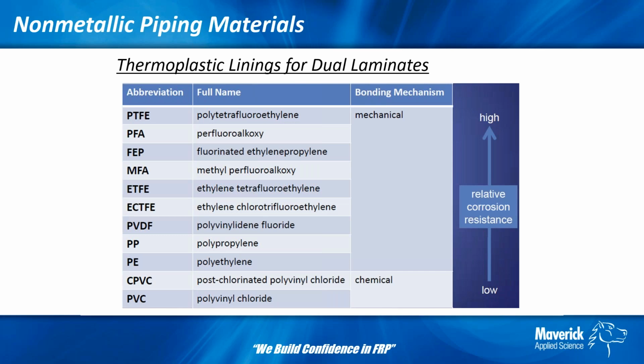But a heat gun can help to kick it off, but at that point it's a very uncontrolled process. You really don't know how much you're getting through, or you might even burn the pipe if you put too much heat to it too quick and too focused in the area. So heat guns really are not a good practice for post curing.